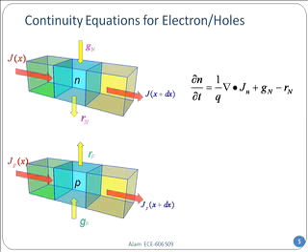And similarly, you will have another equation for the holes. Now, this G sub P, and you realize G sub N for the electron, this is the same flux actually, because the same photon came in and generated electron hole pairs. And so G_N and G_P are generally the same. There are special cases where it can be different, but in this case, we'll assume it's the same. And similarly, R_N and R_P, this is the rate at which electrons disappear. The holes must disappear at the same rate because it's recombining with the holes. So therefore, these two processes are actually coupled.